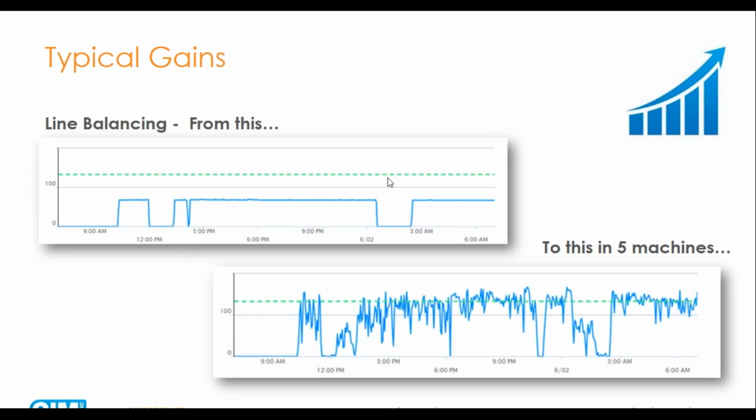There's a couple of issues where we have some downtime, as you'll see here. But when we get up to running, we're running at steady state, and it's nice and frequent. And as the material flows through the line and we get to what is the bottleneck machine on the line here, 5 machines later, we can see that the flow is so much more irregular. We've got overspeeds, we've got underspeeds, we've got overspeeds that cause short stops. We're out of control at that point, and being out of control is not good for automated equipment.